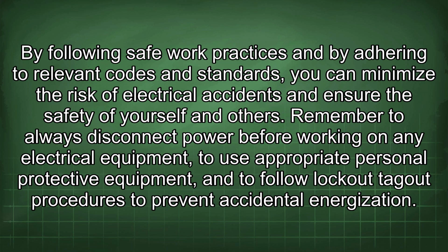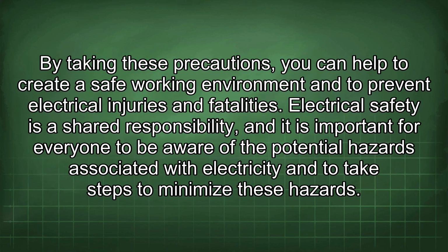Remember to always disconnect power before working on any electrical equipment, to use appropriate personal protective equipment, and to follow lockout-tagout procedures to prevent accidental energization. By taking these precautions, you can help to create a safe working environment and to prevent electrical injuries and fatalities.